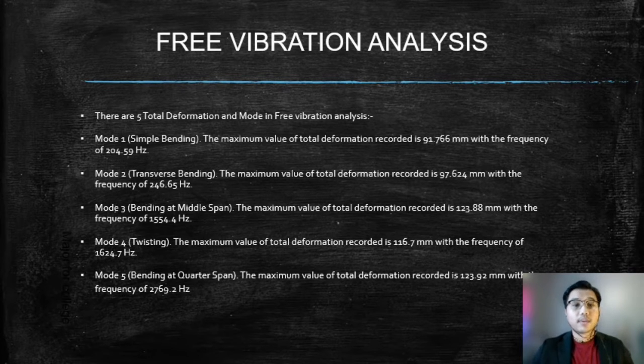There are 5 total deformation modes in free vibration analysis. Mode 1, simple bending. The maximum value of total deformation recorded is 91.766 mm with the frequency of 204.59 Hz.